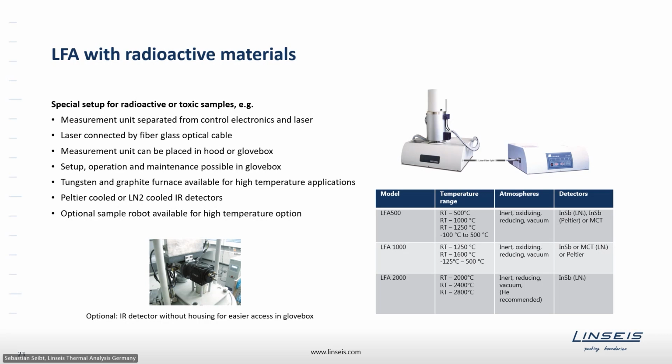And the sample robot is especially useful for the CP measurement mode, as a DSC measurement method typically limits the determination up to 1000 degrees. For higher temperatures, one either needs another method or one can use this comparative method by laser flash. And as mentioned before, the accuracy depends strongly on the compatibility of reference and sample, and also on the measurement conditions.